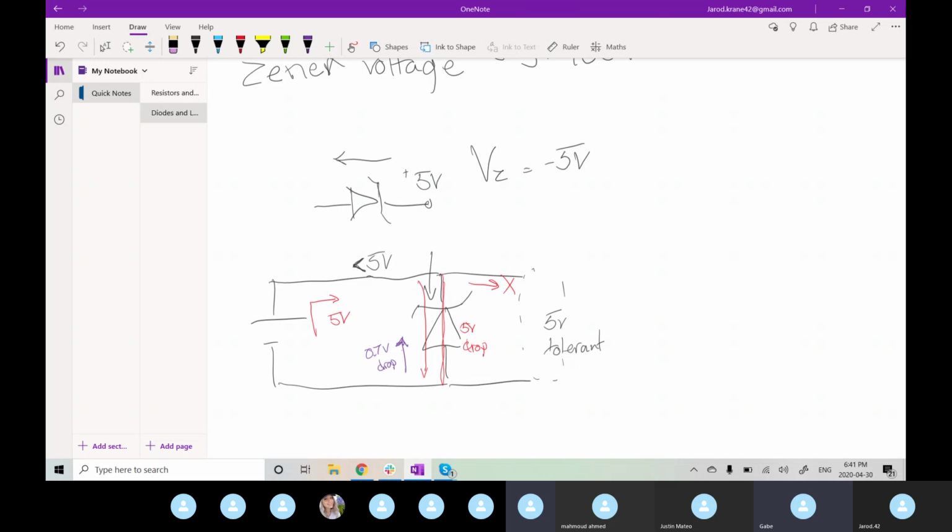So you can use like 24 volts and then send a resistor and then a Zener diode, and then it'll clamp it to 5 maybe, for example. But then that burns a lot of power, so it's not the best. But usually it's whenever you want to clamp some voltage. So over voltage is the most common.